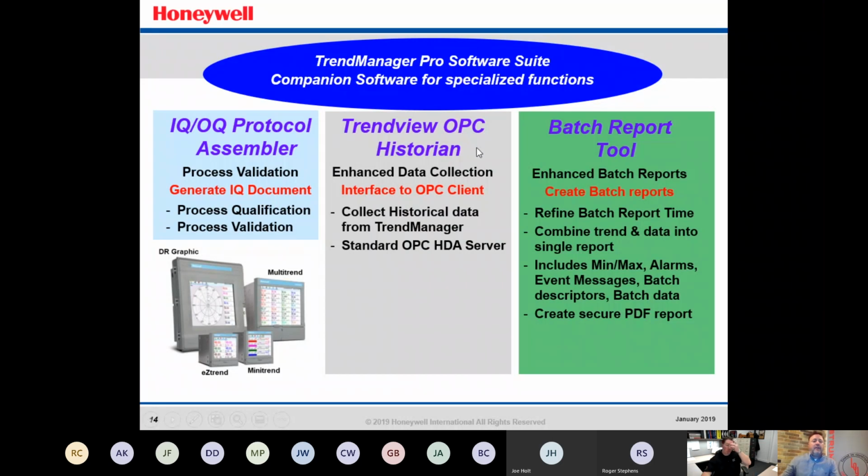TrendView OPC Historian is the next one. If you have a SCADA package that allows OPC communications, this is an interface that allows the recorder to pull in data, or the SCADA system to pull in data from the recorder using the OPC client software.